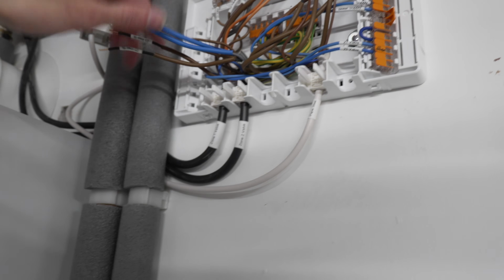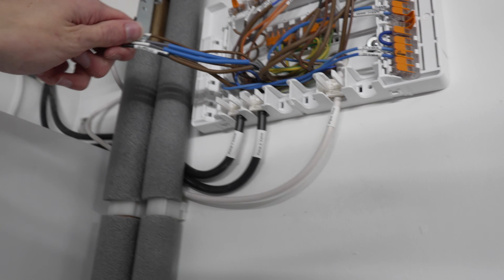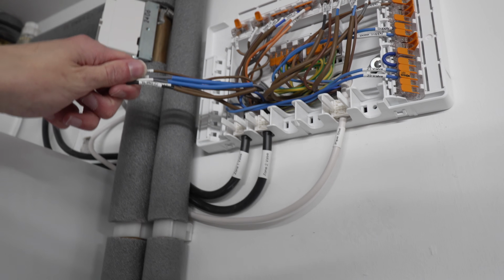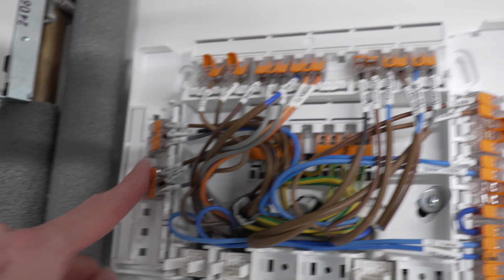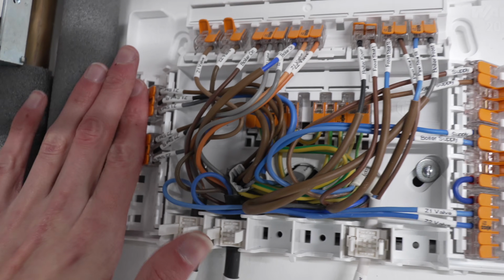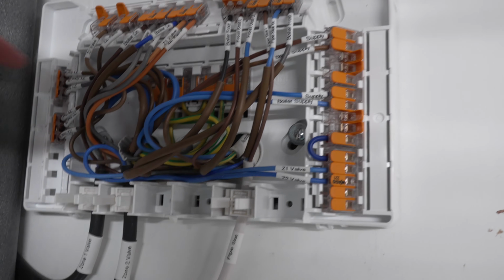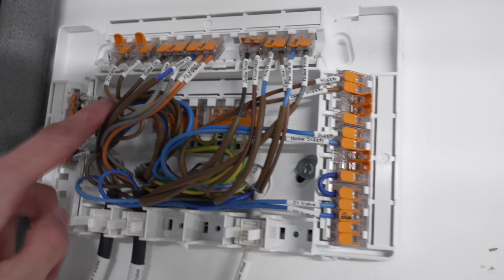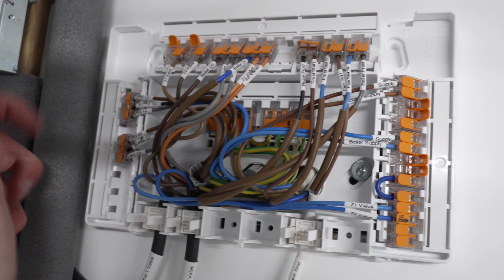So we just need to connect these in a connector block just to make them safe. So they're not currently connected to anything, they're not live, but they're at least kind of available for future use. So there we go, that's those old thermostat wires now neatly put off to the side here in a couple of connectors. I've just put them on the same connectors as each other just to keep them off the side. They're not doing anything, they're just safely out of the way. I've left the CPCs connected because there's no reason not to. The cables are still running through the building, there's still wires here mixing amongst live wires, so it makes sense to keep the CPC and that cable intact. So yep, that's all done there.